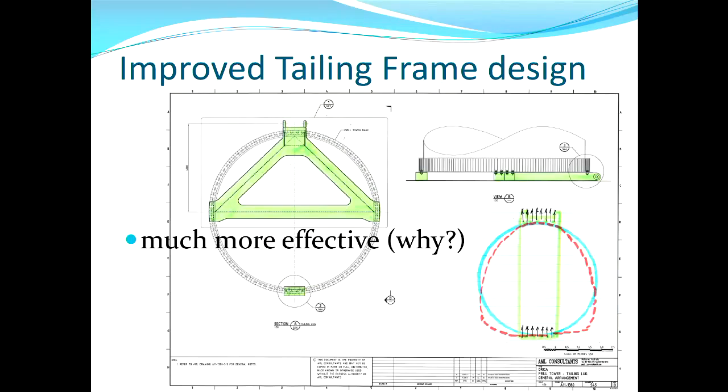We could get an even lighter lifting lug because ultimately the weight of the lifting lug is yet another thing that this huge crane that ends up carrying the whole weight of the prill tower has to be able to support. So you really want the overall lift weight to be minimised. I think we got up to something like 320 tonnes with all the other bits and pieces added.